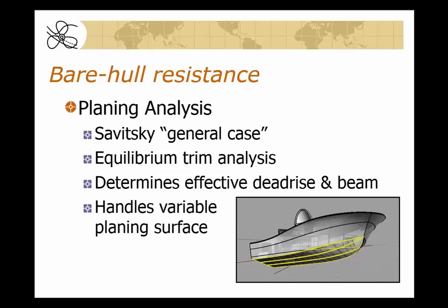Now, one of the characteristics of the Savitsky methodology is that it was based on what was called a prismatic planing surface. And the easiest way to think about that is just a simple wedge. It is a wedge-type shape that was towed in a tank at different angles of trim, and the different lift and drag components were measured and recorded and resolved into underlying equations.